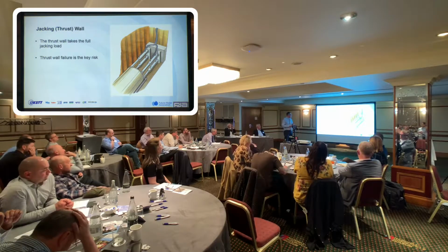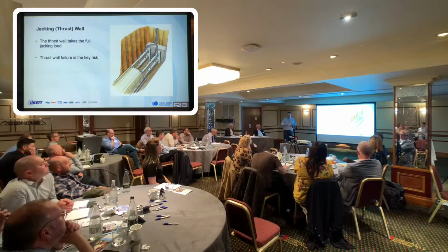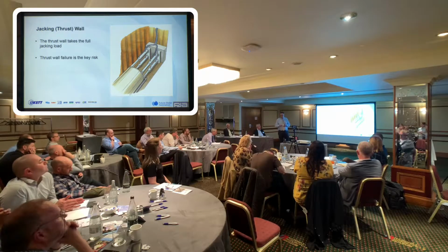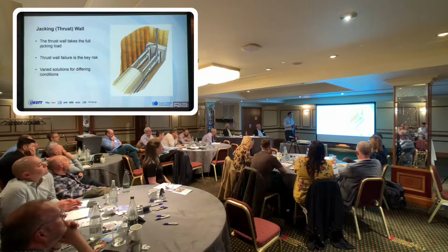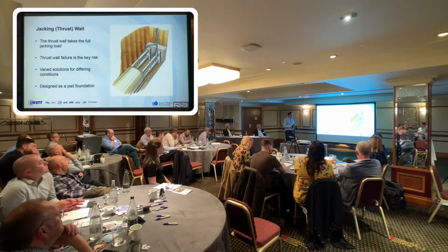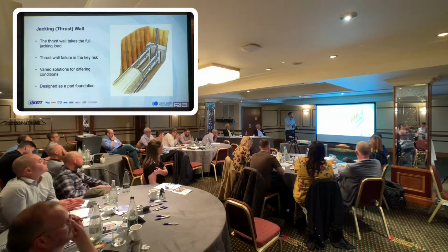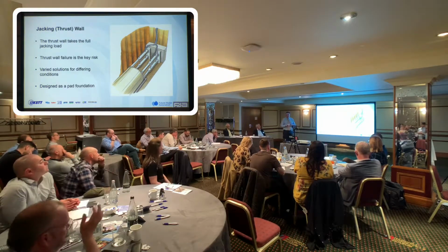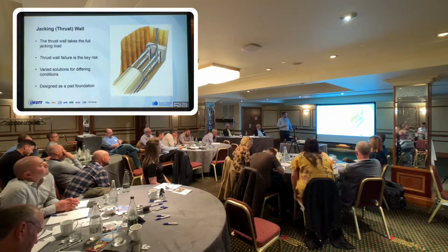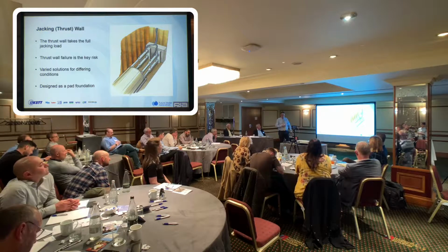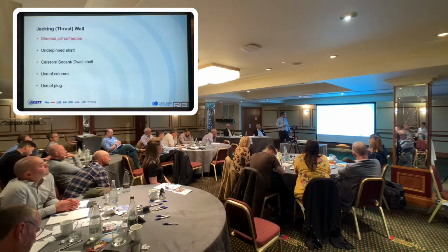The key risk is failure of the thrust wall. I mentioned earlier about making sure that the pit's tight, making sure the back wall's good. If the back wall starts to move, then you're going to compromise the whole system. There are varied solutions for different conditions, but in their simplest form, they're designed as a pad foundation. So if you think about that and turn it on its side, it's a simple bearing failure analysis.